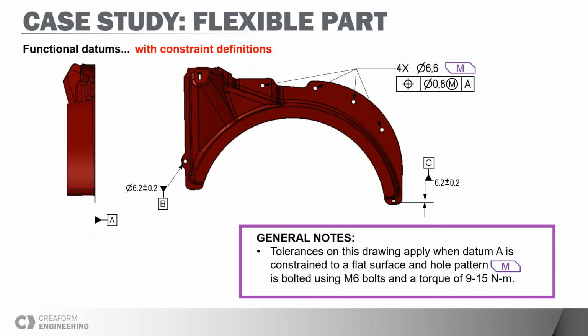You put all these holes in place and make sure it's equivalent to being assembled on the vehicle, and then you can inspect your parts. It's really important to reproduce the natural assembly of the part. That's where selecting datums, and how you choose them, is really important. In flexible components, you have to over-constrain them to a hyperstatic state.